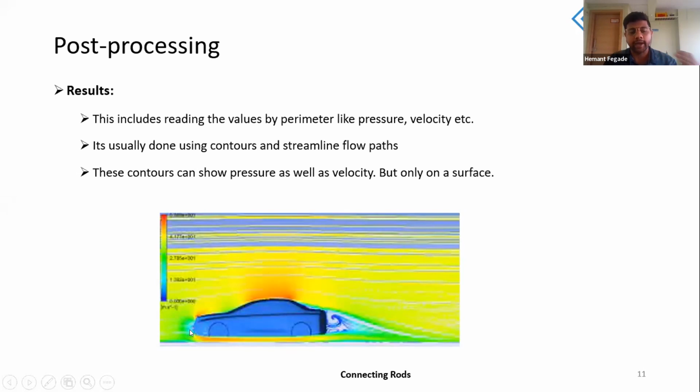Blue means the stagnant velocity; blue is the lowest velocity and red is the highest. That's how the color code works in CFD, where you'll be able to identify the regions where a particular property is concentrated. Here you can see you will have a higher velocity because your air is bouncing off this particular surface, like a push to that air.